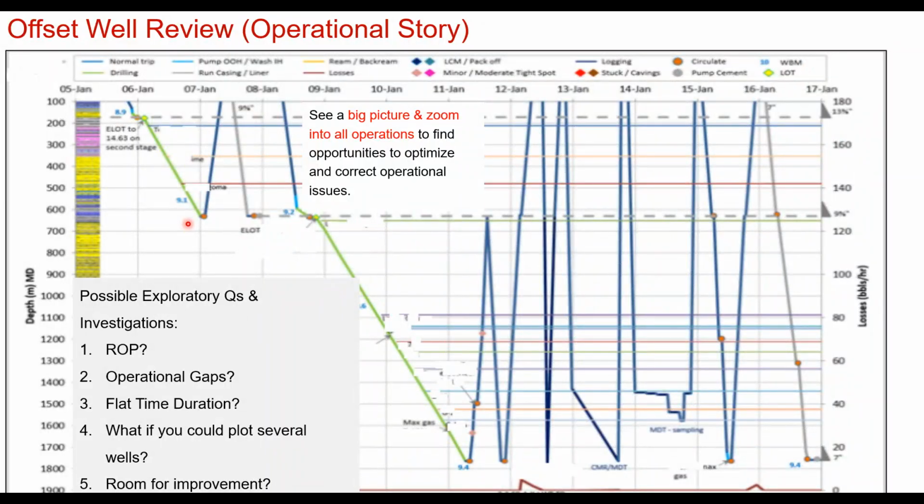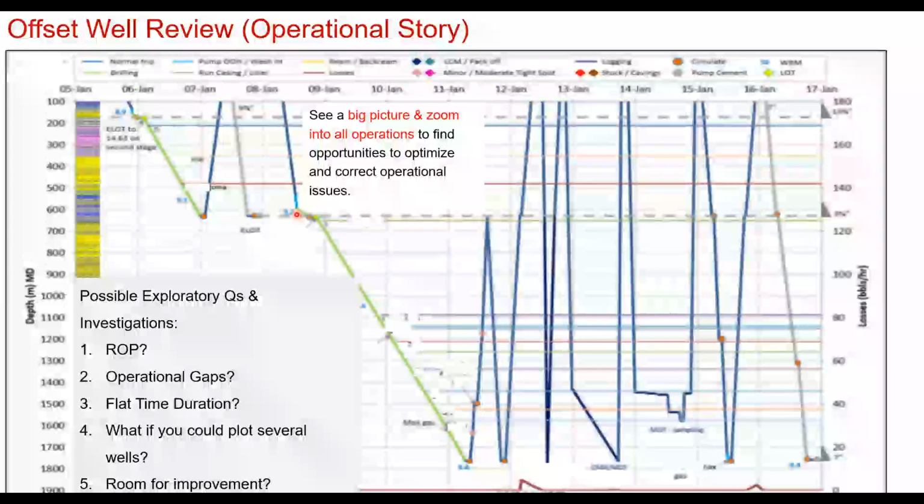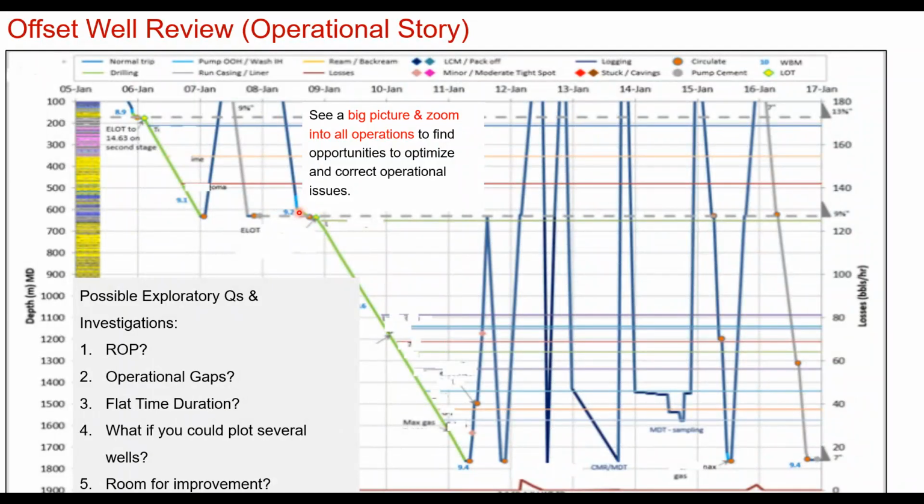If they are not drilling, flat time comes in. There's a flat time here at 650 meter. What were they doing? The slope is slightly less. Actually, you can say they were drilling cement. After cementing the casing, they want to drill out of it. So that's why. And what kind of speed of drilling? You can check it, and then everything was fine. So this is the successful well. Basically, you can see there's no flat time while drilling. If you had a problem, these nice green line slopes will be a step profile, which means they could not drill at certain depths.